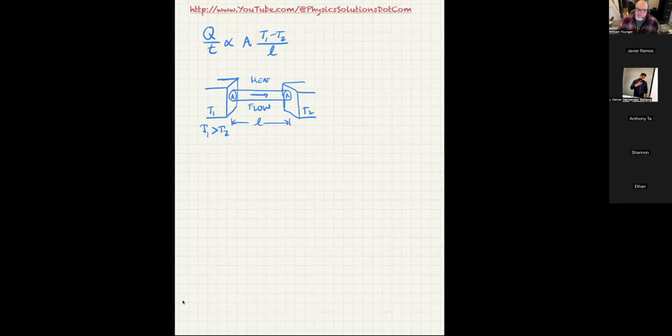It's basically dT over dx, where the numerator T is capital T for temperature, and the bottom is x, for thickness, but you could use just plain x. So this would be dT over dx, and that's what we call a gradient. Now, you can also add a constant of proportionality that would make it into an equation.